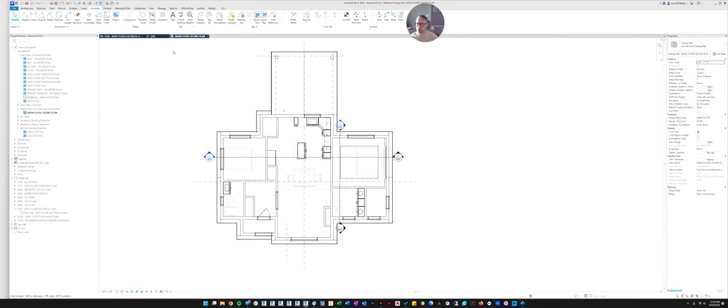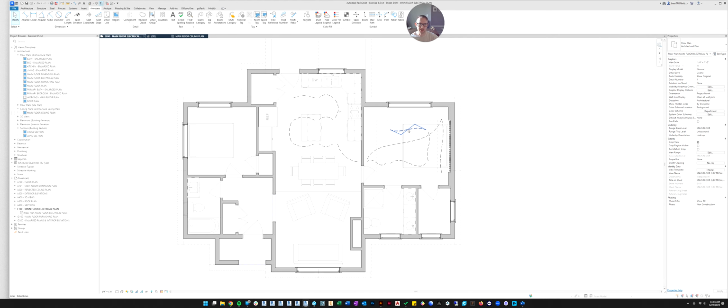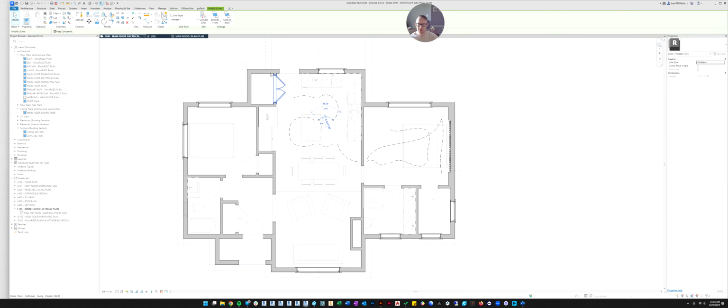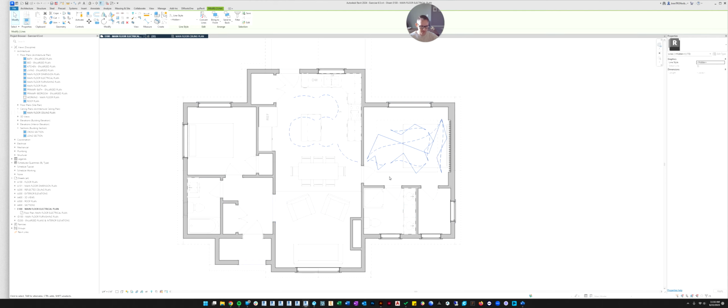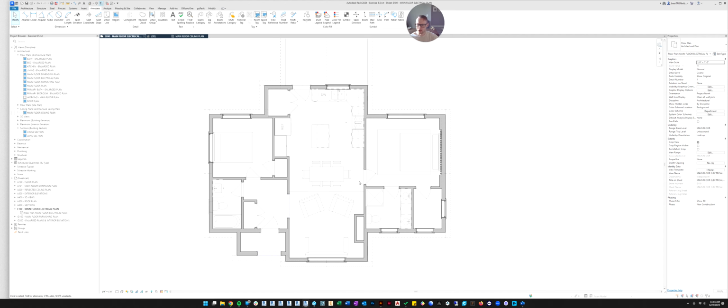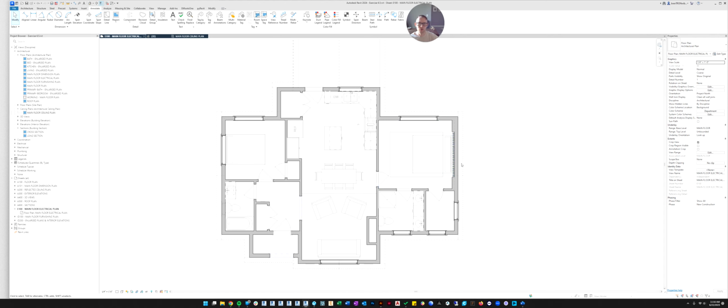All right, so now let's go back to our electrical plan, and the last thing we need to delete are all these lines. So we'll right click. Actually, we can still mass select again, hit the filter button and check none. And you see how it says lines hidden? So it says they're lines and it tells you what type of lines. We can select all of those and just hit delete. All right, so now we've cleaned it up. Now let's do an easier way.